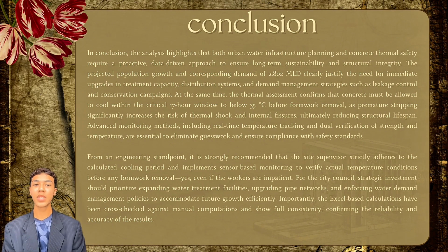So, the source outlined a strategic shift required to accommodate a growing population, emphasizing that infrastructure must be proactive rather than reactive. By the year 2040, the population is expected to reach 18,680 people. This isn't just a number, it represents a specific resource requirement of 2.8 million liters per day of water needed. So, infrastructure requirements need to meet these demands.